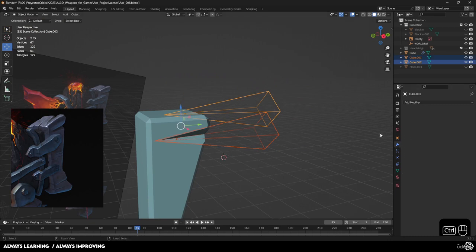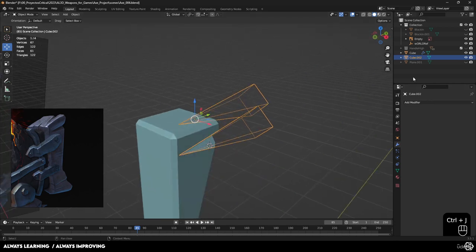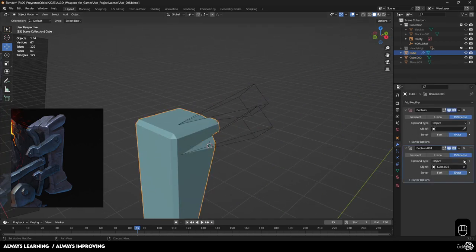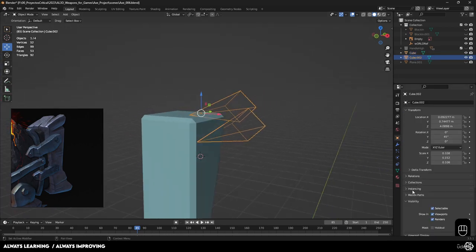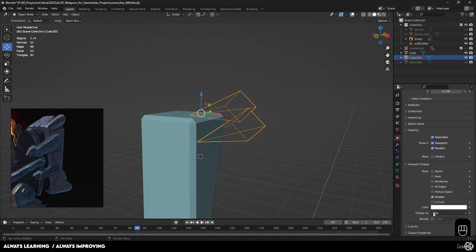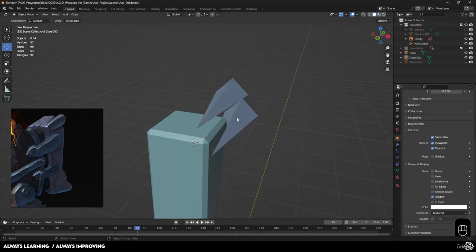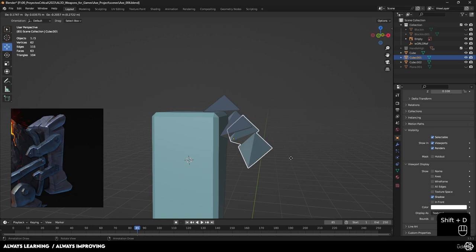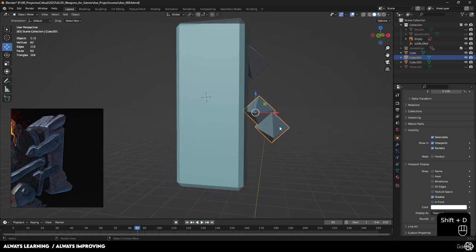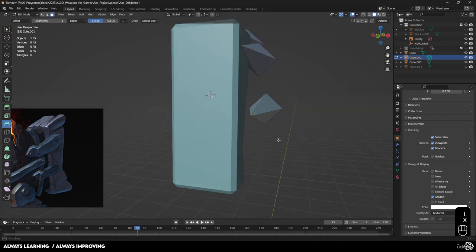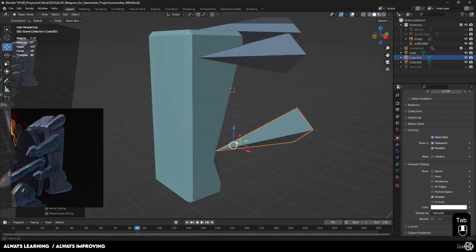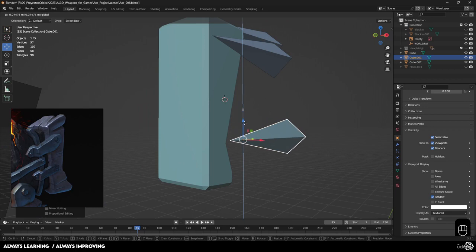Another option that I honestly like to do, and this is what I'm about to do right now, is I'm just going to Control J both of them. As you can see, this cube is still reading one Boolean from cube 2, so it's working. But let me eliminate that one for just a second. Bring these guys back to the visibility of just texture or solid. And then I'm going to Shift D. Let me grab all of the linked faces of one and delete. There we go. And now this one, as you can see, there's another big one right around here.